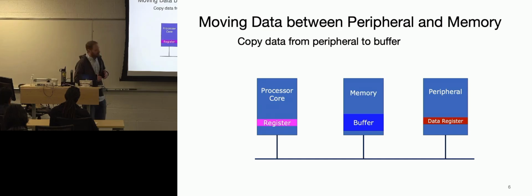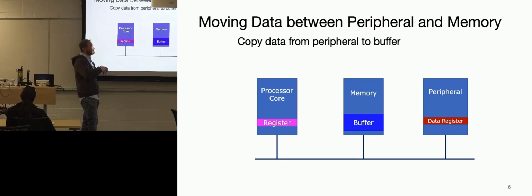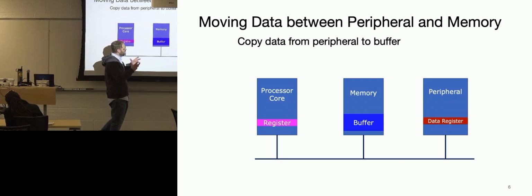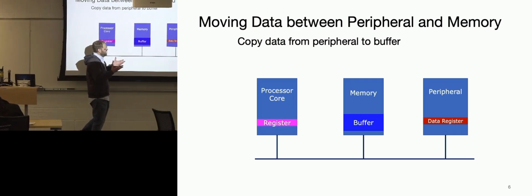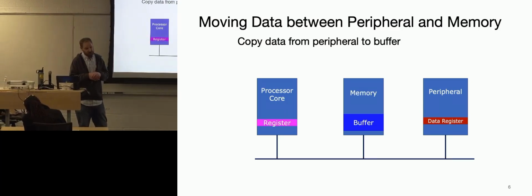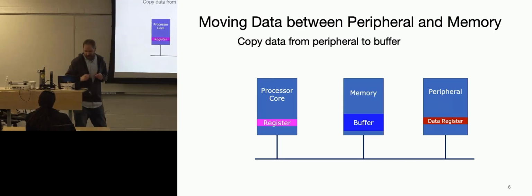So the problem that we typically face is, say you have some peripheral out here, say it's an ADC and you're sampling something, and your goal really is to take the average, min, max, that sort of thing. You'll use not the actual ADC value itself, but some mathematical average of it. So what could that be? Maybe there's some analog brightness you want to follow, like the sun. You might want to take multiple ADC values so that you know exactly which angle the thing's at.